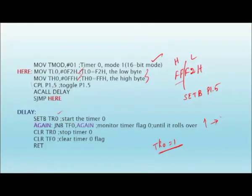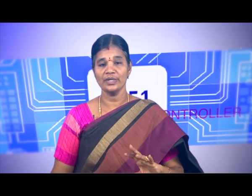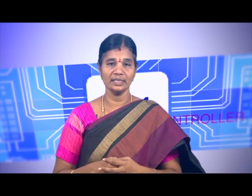After reaching the maximum value, the timer overflow flag becomes 1. Once the timer overflow flag occurs, it exits from the loop, then it clears TR0 to 0, then clears TF0 to 0. After clearing, it returns back and the same process is repeated. So in the program, we have to initialize the timer, then till overflow occurs the same process is repeated. Once the overflow occurs, we have to stop the timer and also clear the overflow flag. For that we are using the CLR instruction.